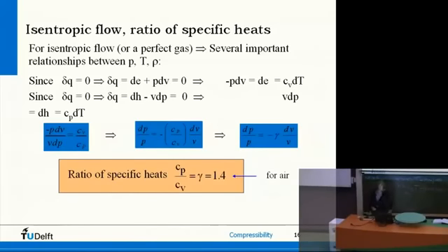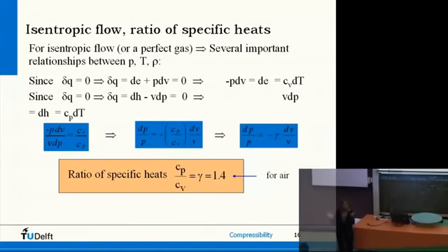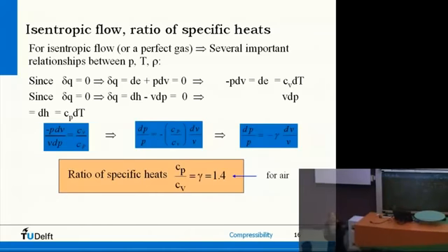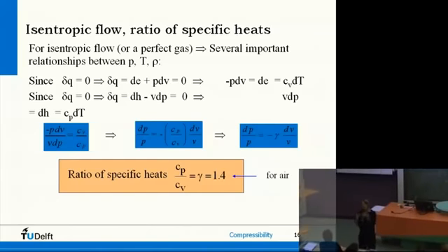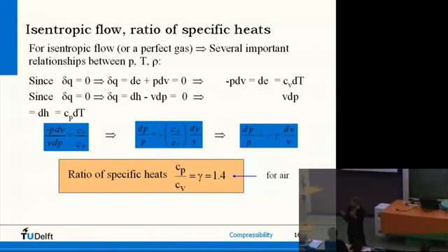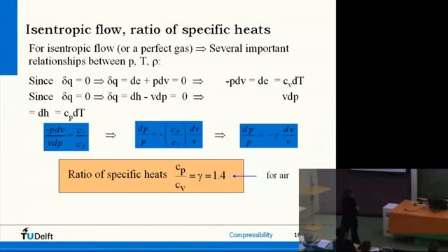I'm going to use this in more instances, but the first thing you can do from this is derive, because the problem I have here, I have pressures, densities, temperatures. 3 unknowns, 2 equations. If I manipulate them in such a way that I can eliminate one and end up with 2 unknowns, it's more interesting because I already had the equation of state. P is rho RT, so pressures, densities, and temperatures. What I'm looking for now is a relation between, say, temperatures and densities, for example.